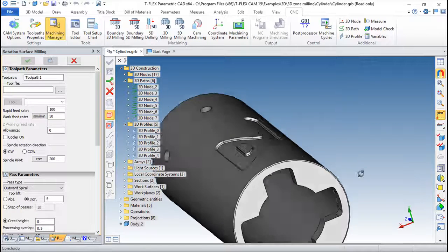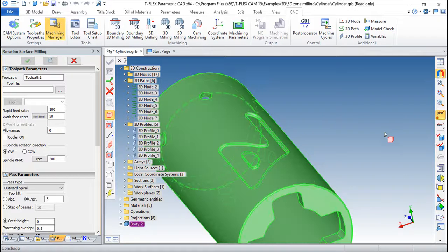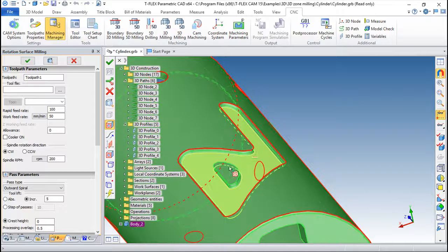We can select this in several ways, but we need to choose our solid, so all of it, and I can continue if I simply select the face that I want to mill. So this one, okay? The face recognizes this internal island, so it is okay.